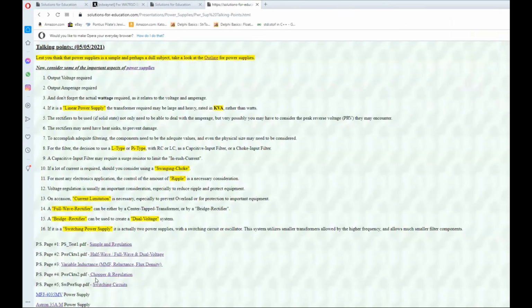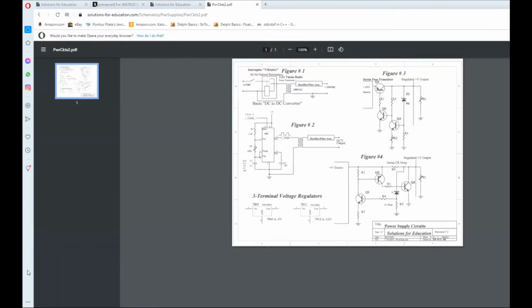Here's something that the older guys in the group would be interested in. Back in the days of the 50s, when you had a radio in your console and you turned it on, you would hear a hum in the dash. That's because there was a device in there that looked like a large capacitor, but it was a 4-pronged device, and it was a vibrator. Your radio requires about 250 volts for the tubes, and you got 6 volts. This is before 12-volt systems: 6-volt batteries, 6-volt radio, and this thing in here just humming away.